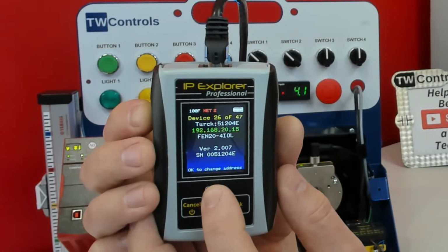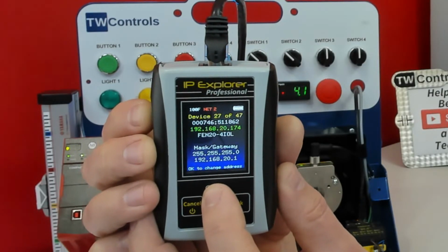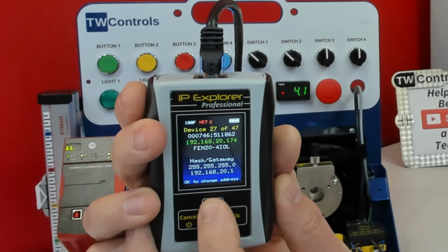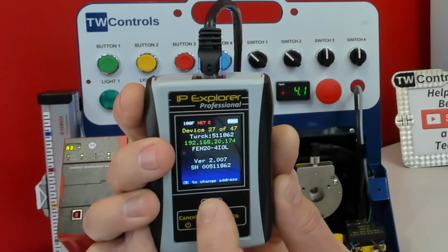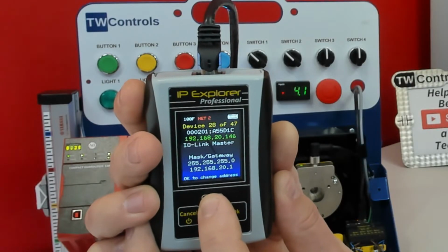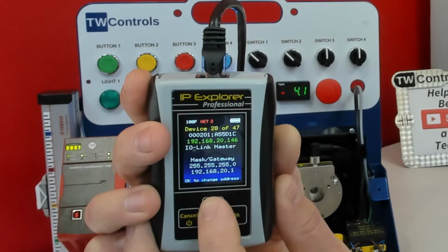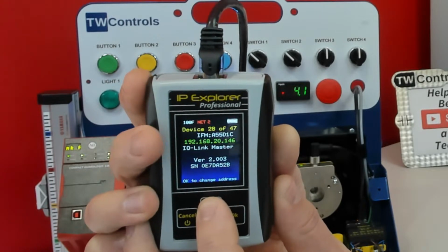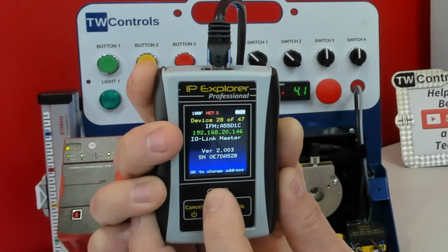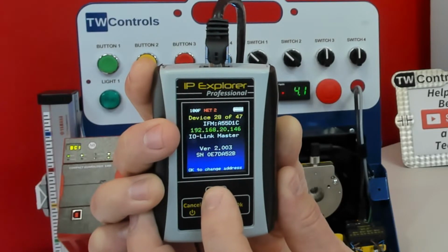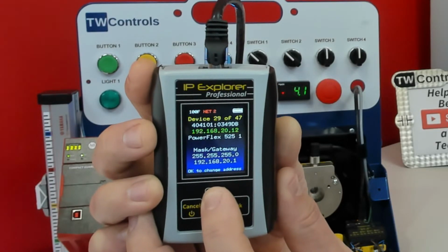There's a FIN20. This is what a Turck IO-Link module looks like. So it's only what they report. It's all we get. So we can tell it's a Turck by the MAC, and then they just report their model number. IO-Link Master. I'm not going to mention this. Oh well, I guess I am going to mention this brand because it says it up there, but IFM would be great if you could report a little bit better right there. You got an awesome IO-Link module, but yeah, IO-Link Master doesn't tell us a lot.